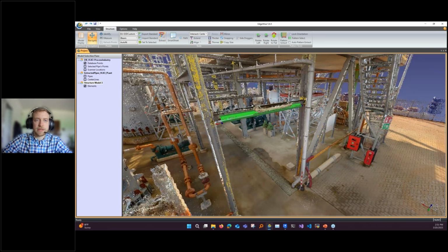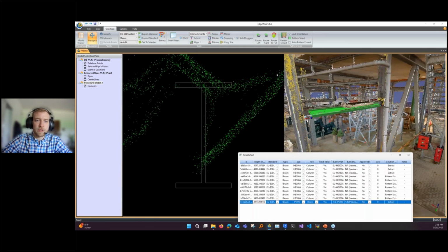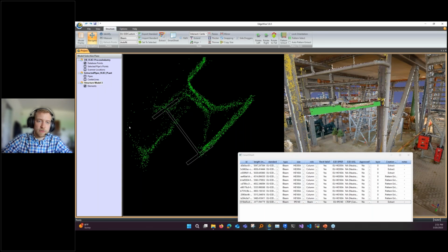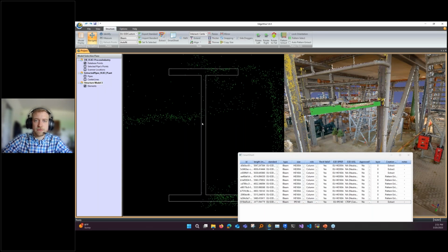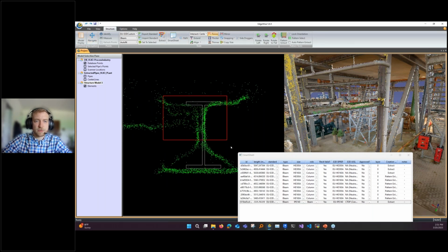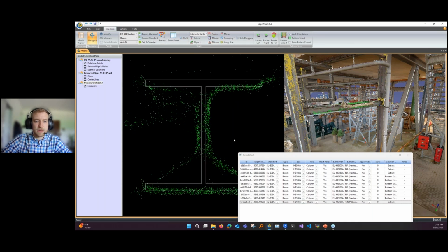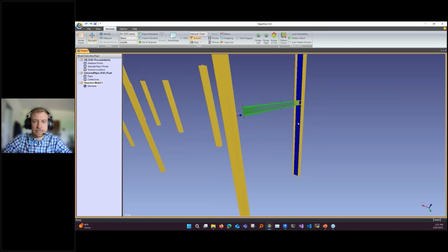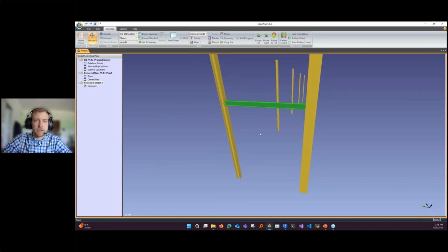And didn't quite get it right, but we'll just do a quick tweak. So if you hold Control, you can do a rotate there. There's also a rotate to flat, which can be nice. Refit is also very nice, which will straighten it up for the point cloud. And so we'll get a bigger guy here. And that looks reasonable. We've got our extend functions. We're going to extend with the C key on the keyboard.